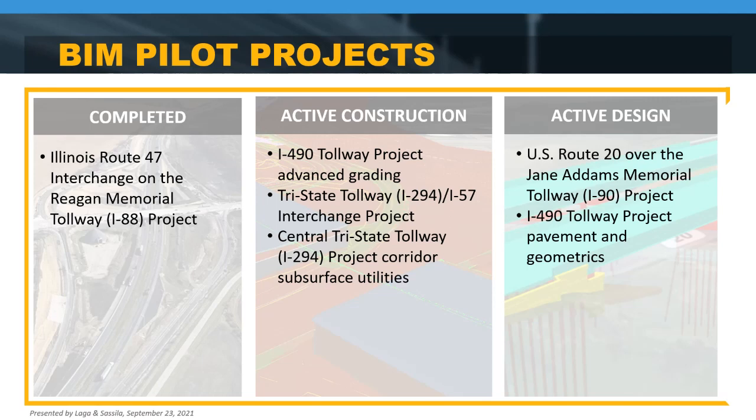Being more model-centric, we eliminated cross-section sheets and drainage profiles from the printed drawings and placed the model in the contract hierarchy. We worked with industry to identify the appropriate deliverables for contractors, including file types such as XMLs and DGNs. With the advertisement, we securely locked the models and worked out a solution similar to other states for signing and sealing them. In construction, we worked with the contractor to identify field changes and adjust quantities accurately and timely. In doing so, we coordinated heavily with the designer for the required model changes.